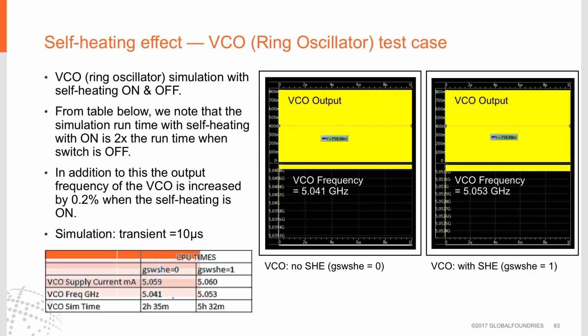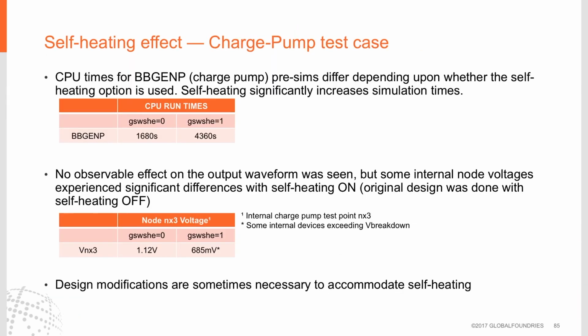In the case of a charge pump, we actually did find one of the stages was affected by self-heating, and we had to go back and correct this. Self-heating being turned on identified the problem. Again, the simulation time is dramatically longer.